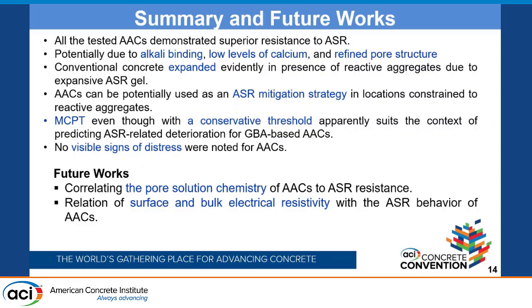To summarize everything I presented, we noticed that all the tested alkali-activated concretes gave us superior resistance to ASR as compared to the conventional ones. The conventional ones expanded evidently, and this is due to the presence of expansive ASR gel.